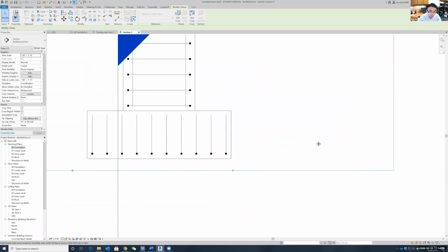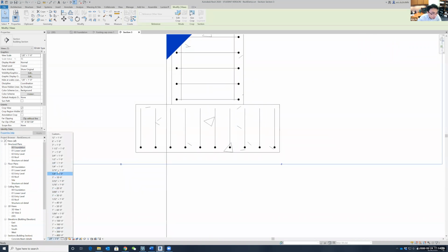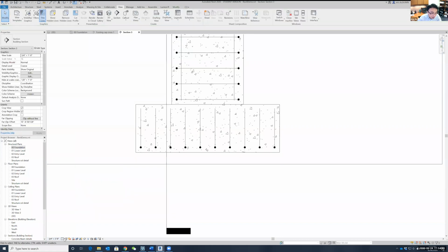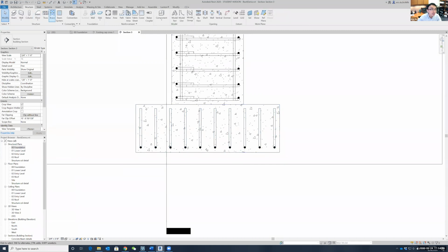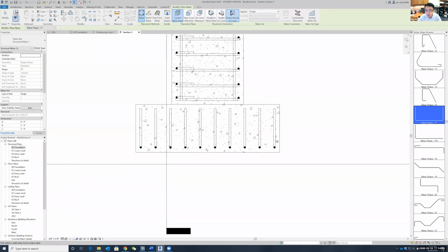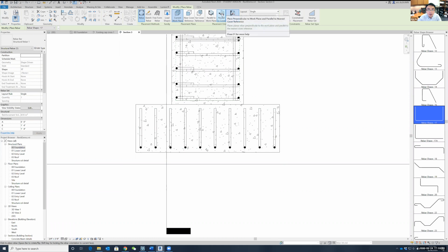Of course, I want to change the view scale to 3/4 to 1. Well, frame should be fine, but maybe one here. All right, so now I want to build my rebar, the same rebar in this direction. So I'm going to structure, rebar, same rebar, and I change it back to parallel. No, parallel to work plan. This is my current work plan. I can place it here like this, right? Okay, and then I can change it to maximum spacing, the same thing, enter.